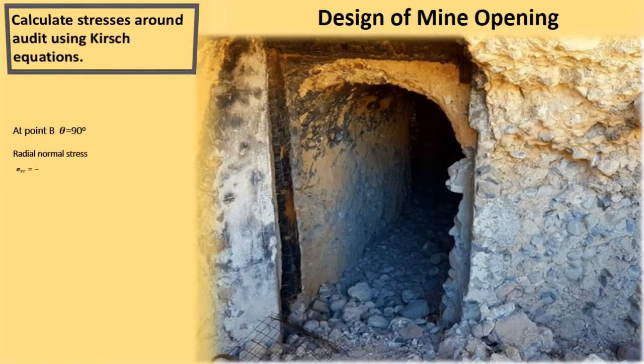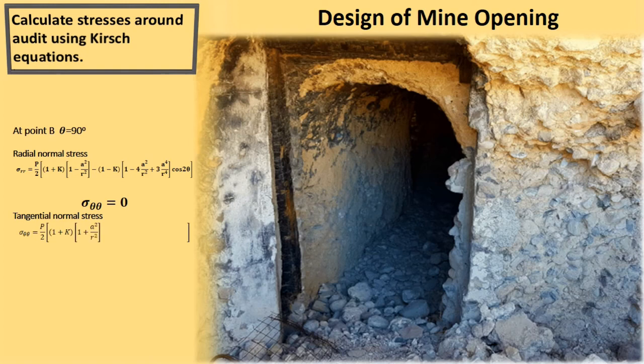At point P, where the theta is 90 degree, the radial stress is also 0, and also the shear stress is also 0, and the tangential normal stress has the value of 1.98 megapascal.